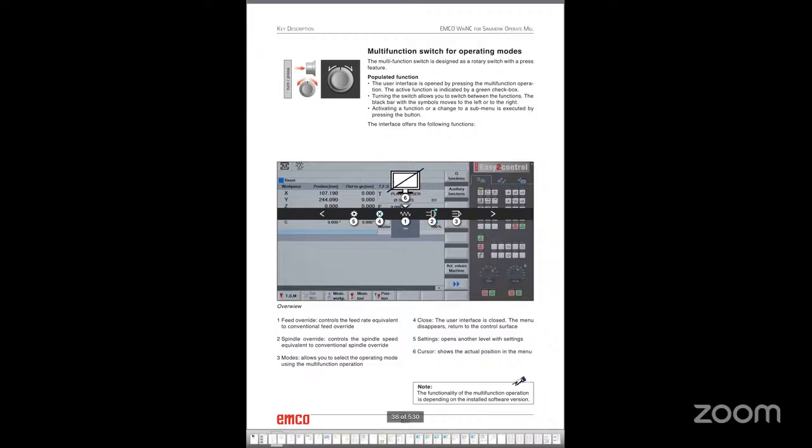So here we have, for example, this one. This one represents the feed override. That means you can increase or decrease the feed rate in your program. Say 50%, 100%, 120%. First, check the trial run, then check the toolpath and also control the machining speed. Say, for example, like this. Which one is the feed? Yeah, feed.